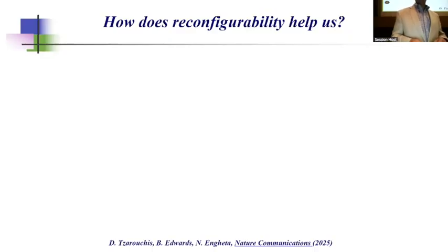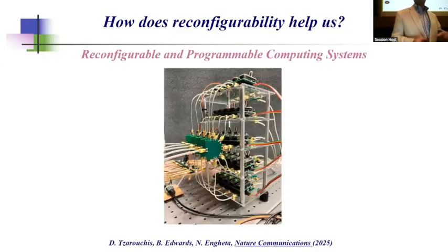In order to answer that question, we decided to build this system entirely in the RF. There's no light over here. It's entirely an RF, 45 megahertz system. This system that you see over here consists of 25 units, representing a 5 by 5 matrix. Now, each unit, we call it a multiplier. Each unit consists of an amplifier or attenuator and a phase shifter, commercially available. This is the 45 megahertz RF.